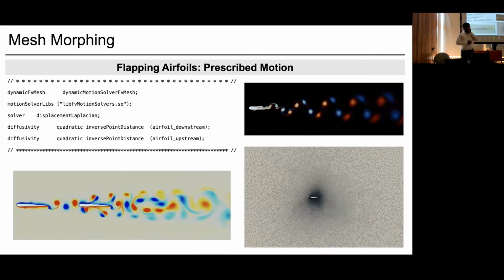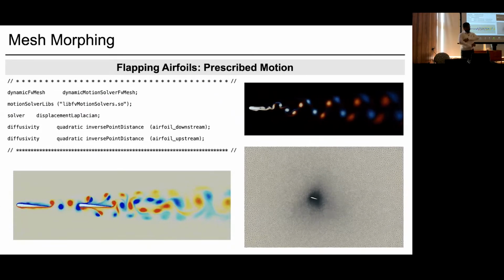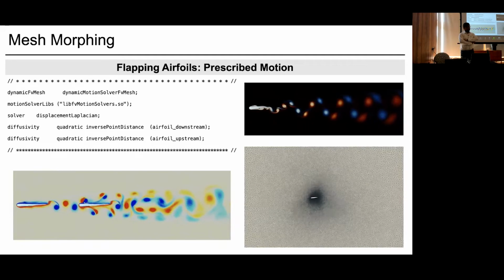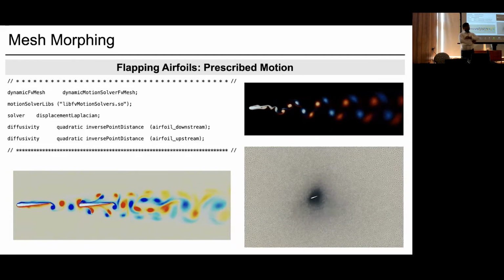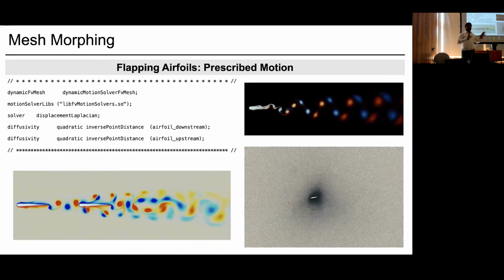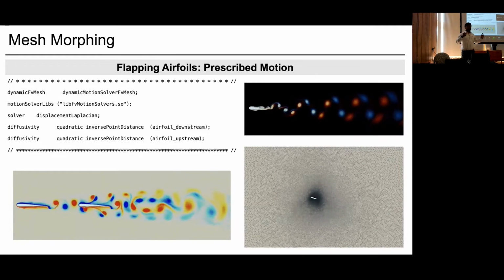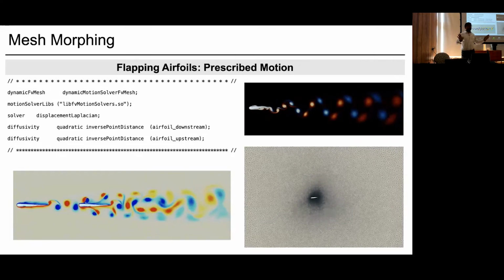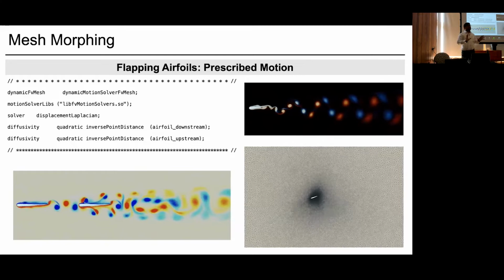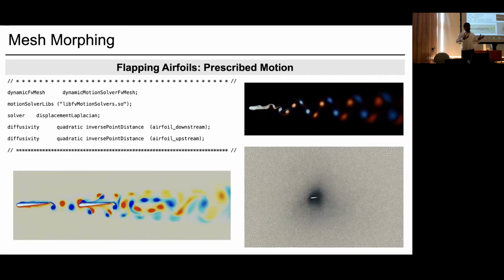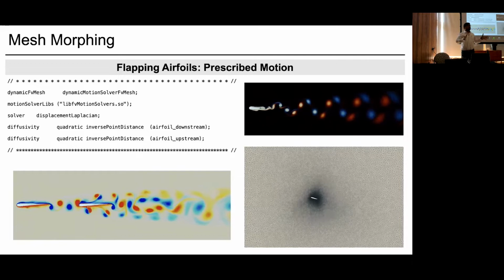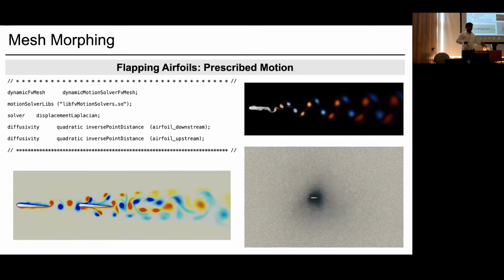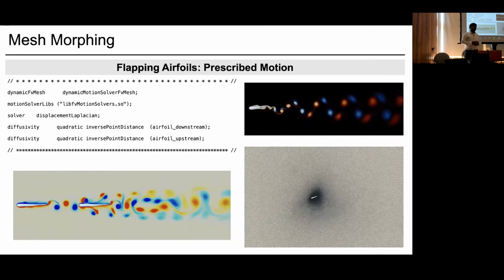Well, for example, in our case here, there is no background mesh. There is a single mesh, because within the boundary there are no cells, right? So there is a single mesh for mesh morphing, and the whole mesh is getting morphed throughout the domain, unless you constrict it up to a certain diameter or certain distance.